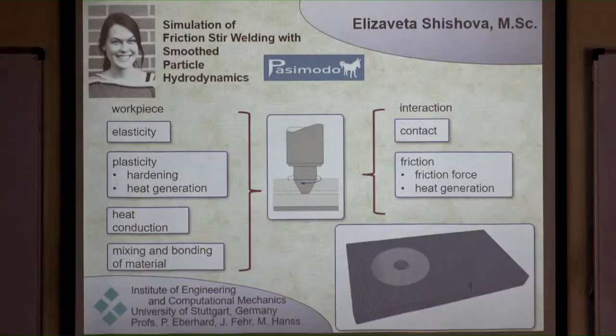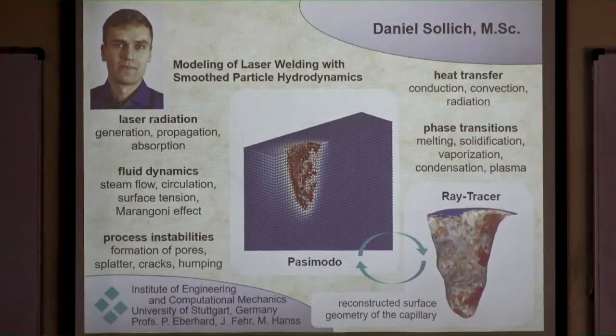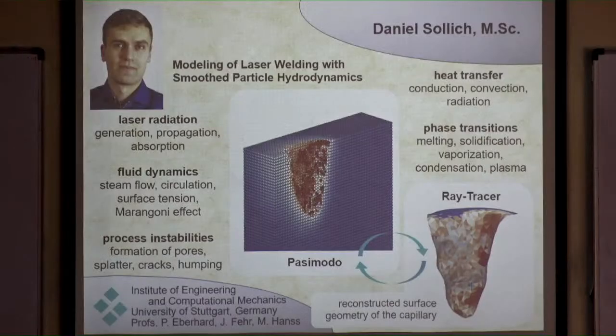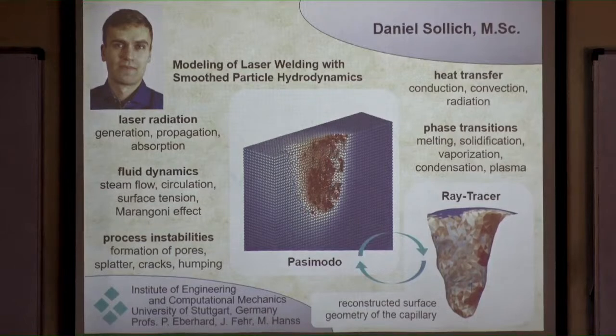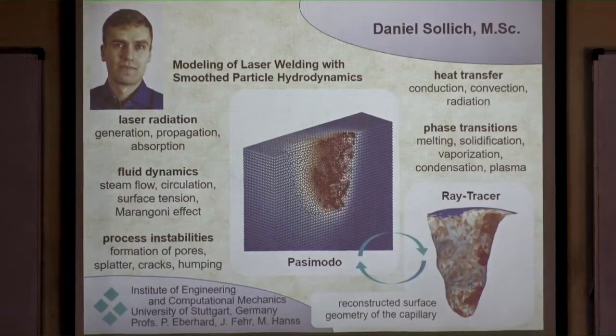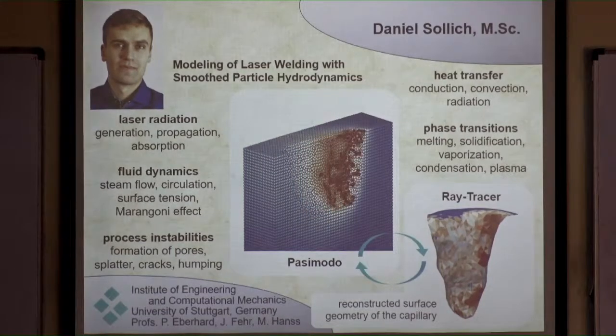And so you want to simulate in one simulation environment the mechanical behavior, the thermal behavior, and many more things. And this is complicated. Or here, laser welding. What is the idea behind laser welding? You direct a laser ray with high energy to a surface of material, and then the surface is melting. The material is melting. And then you move the laser ray.